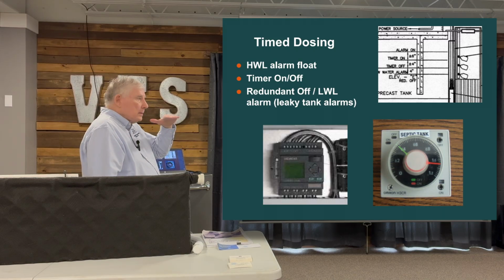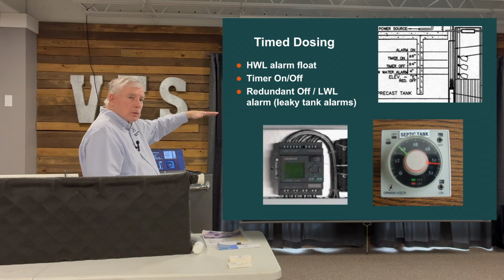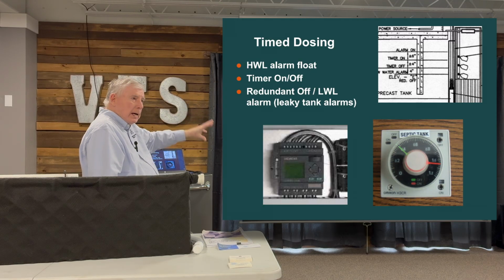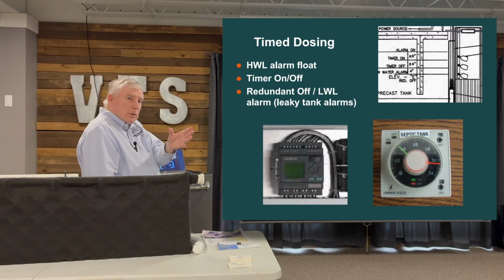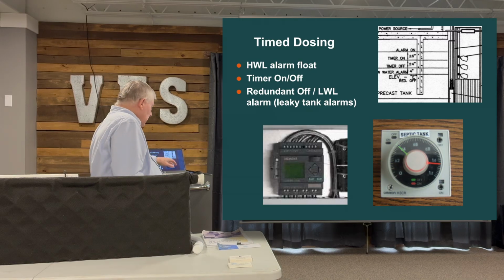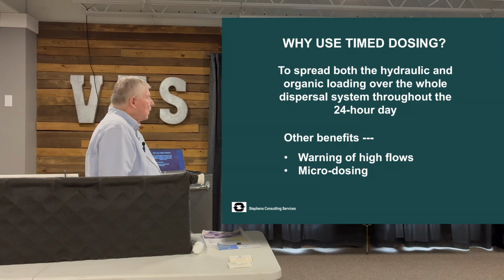Set the timer in the pump in the tank, it controls the time the pump runs when it's on, and the time it waits between doses when it's off. So those two settings are on these old timers. Today we got MVP panels that go in, little digital monitors, that have that and a whole lot of other bells and whistles. Mike will tell you more about that.